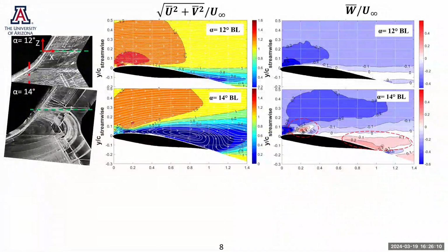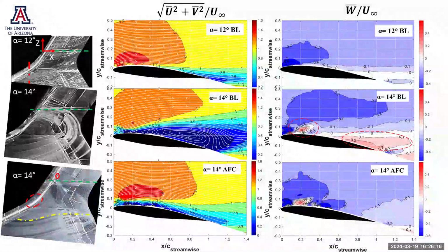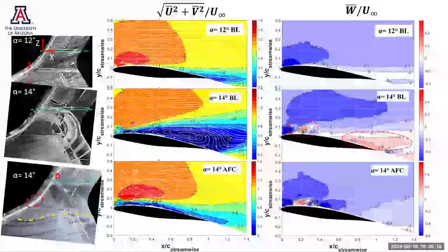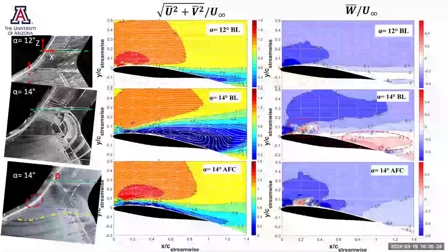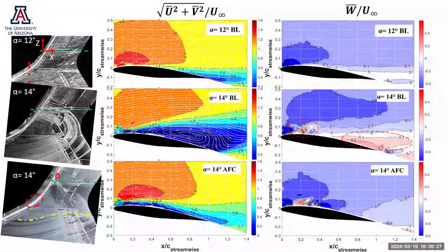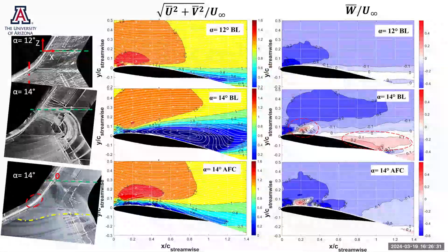With AFC, that is with this supersonic jet, we were able to almost completely get rid of that recirculating region and reinstate that flow acceleration that was missing. To complement it, the outboard flow that was dominant in the rear part of the wing is eliminated.